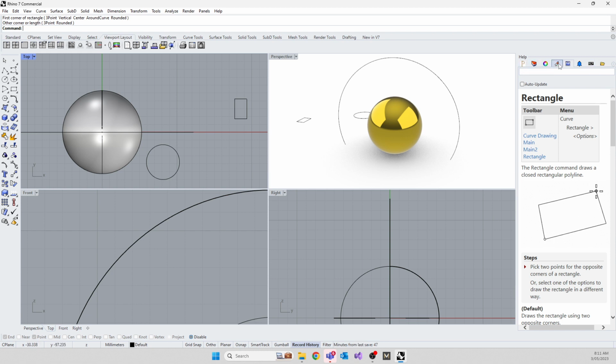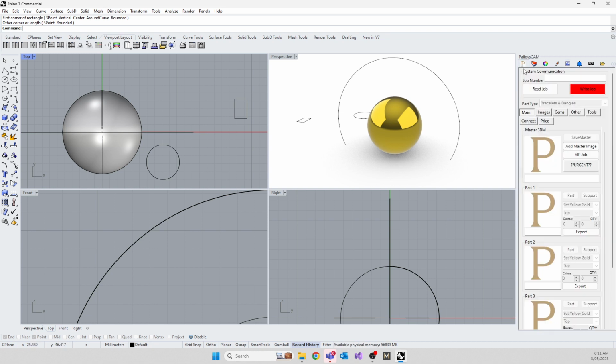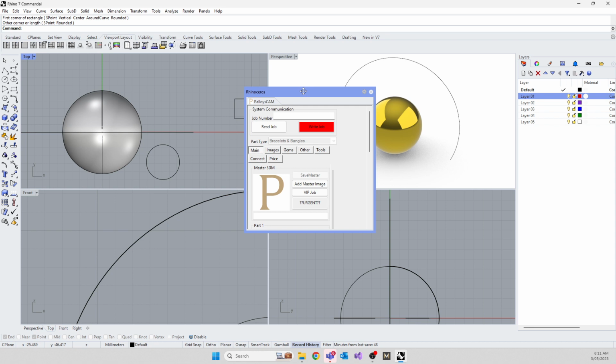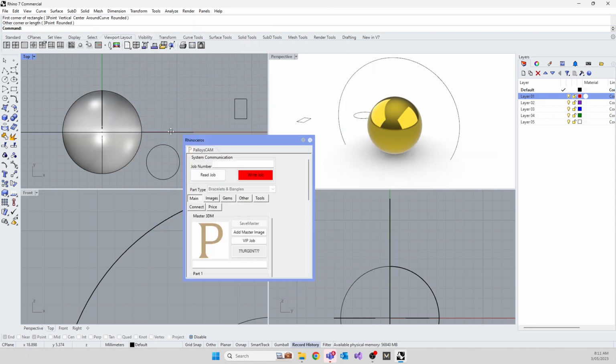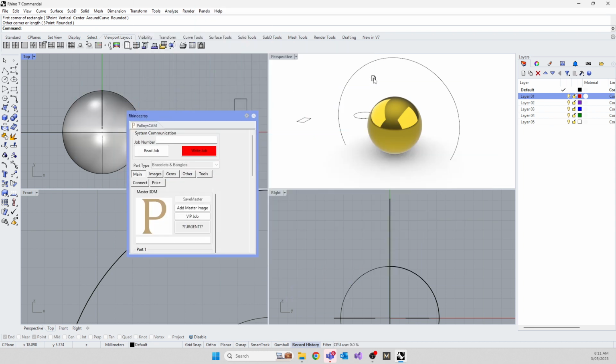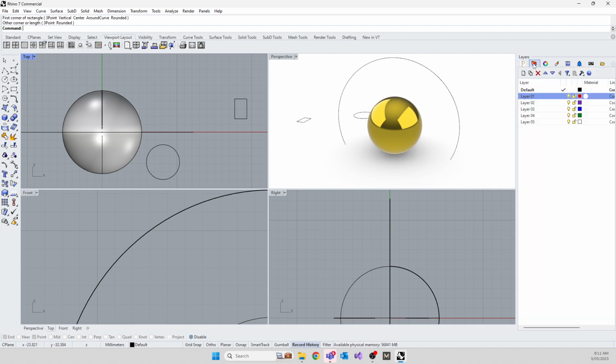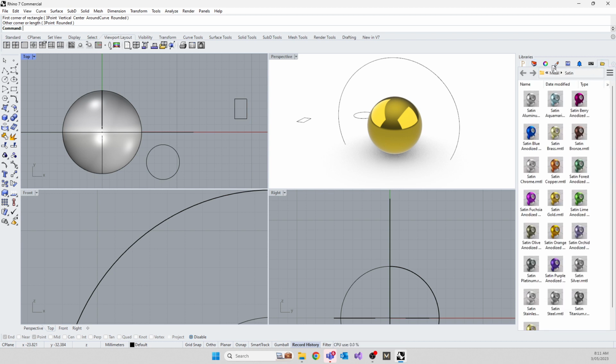How to dock stuff in here or not dock stuff in here is quite easy. If you would know from using a plugin, if you have two screens, you can take the plugin, grab it by its name up the top, and move it out. And now you can move that off your screen to another screen if you need to maximize your screen space. If you want to put it back in, grab it by its name, not the top word Rhinoceros. That's its window. You want to grab the toolbar by its name and move it, and dock it here, or you could dock it up there, or wherever you want to dock it. Similarly, you can move your stuff to what you need the most. So layers is my second most used thing. I want to move it forward a little bit, and then my libraries are there, so move it back and forward.